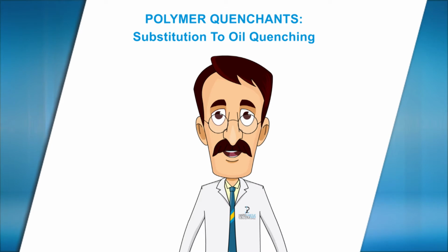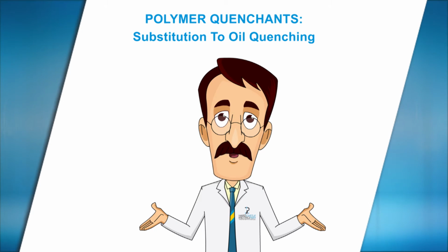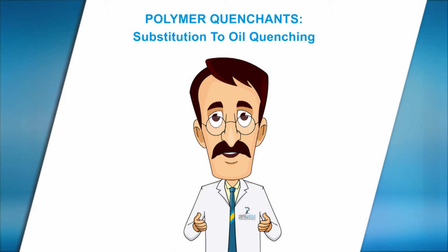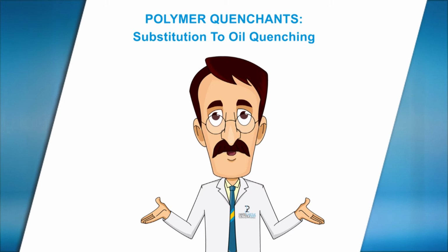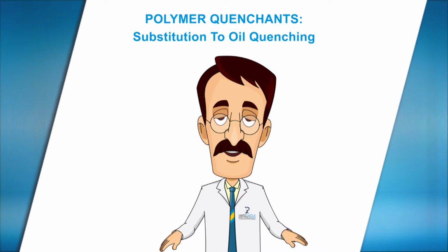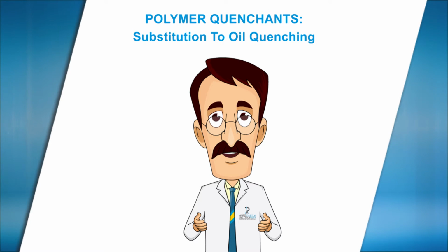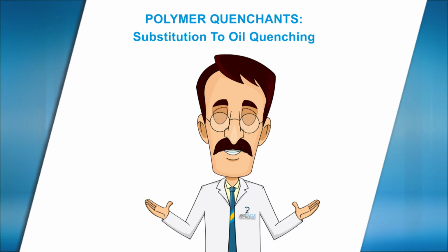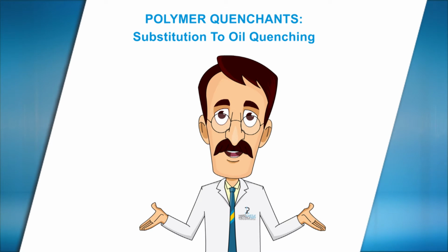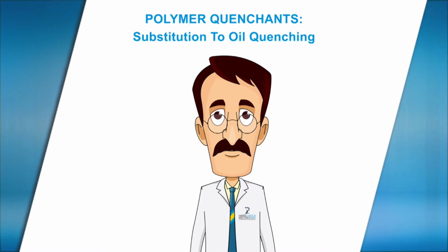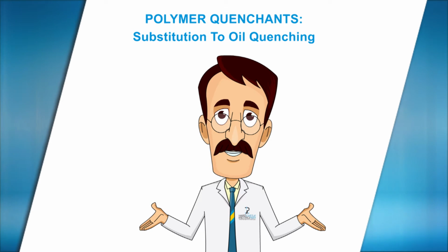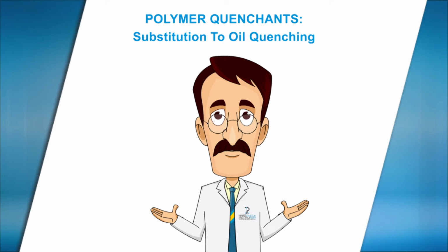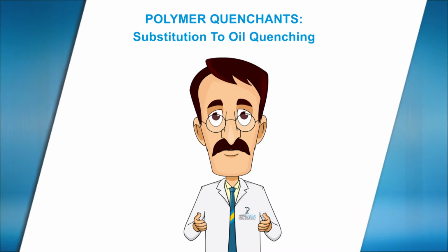As a result of our continuous development programs, we are today able to offer users a complete range of water-miscible quenchants which successfully covers the whole spectrum from oil to water quenching. Accelerated quenching oils can already be replaced in a wide range of applications as polymer solutions are available, which give comparable cooling characteristics. These solutions are therefore suitable for hardening alloyed quench and tempering steels and some tool steels, as well as for quenching components directly from forging.